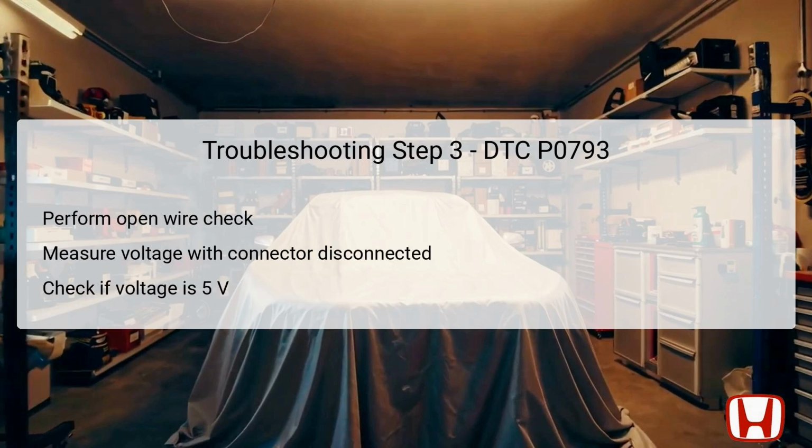Step 3 focuses on evaluating the VCC1 line for continuity and voltage stability. With the ignition switch set to the on position and the CVT drive pulley speed sensor 3P connector still disconnected, measure the voltage again, this time between test points designated for the VCC1 circuit.